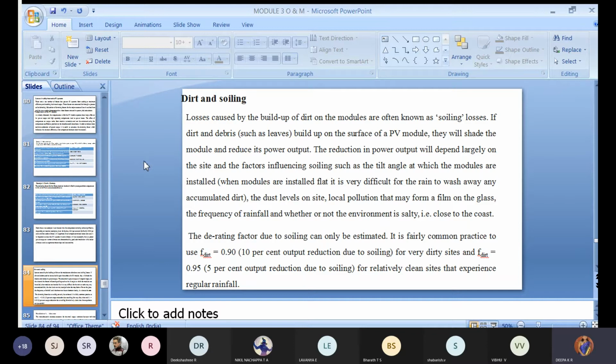And due to that, your cell efficiency of receiving the irradiation will go down technically. And of course, from the outer look, it is going to create layers. Layers mean the receiving capacity of the collectors will reduce. It acts as a shadow, covering the surface. So due to that, your conversion of energy will definitely reduce. So here, that overall part of dust accumulation on the surface, we'll separate the concept. Dust and dirt is one concept. Dust accumulation over the surface of a module, we call that soiling. And due to that, your output will not reach the expected level. So it is creating a loss. You can call that soiling losses.